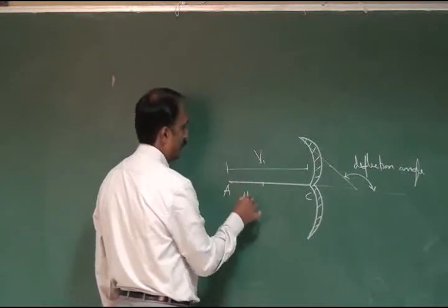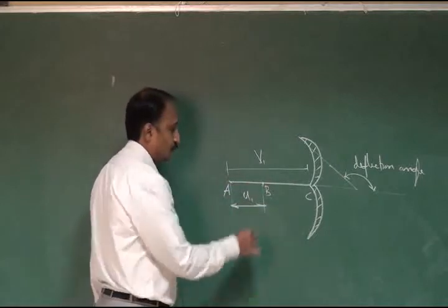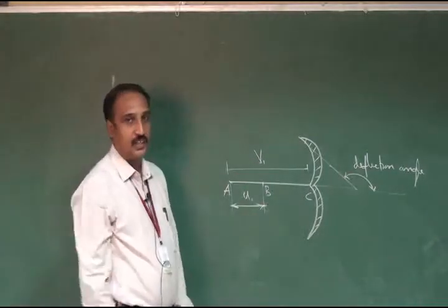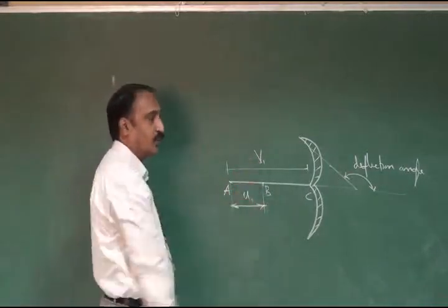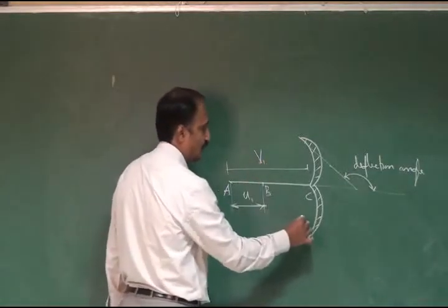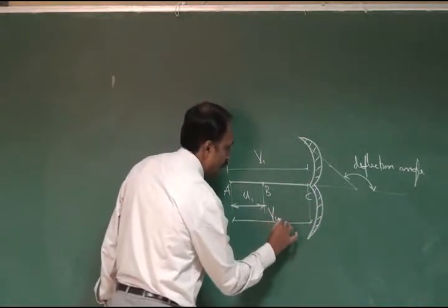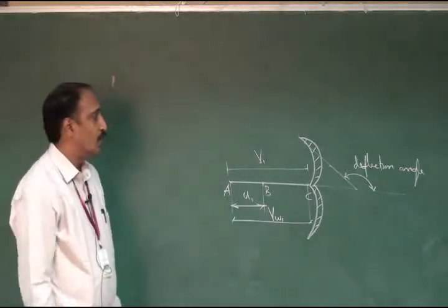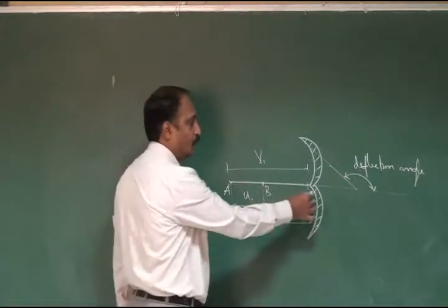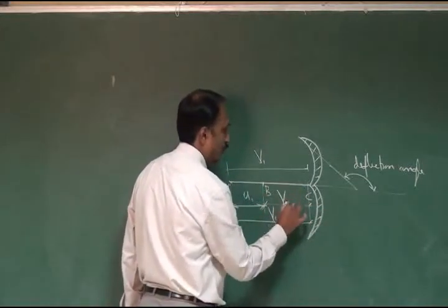This is the tangential velocity vector. Now absolute velocity is a horizontal component. There is no vertical component of the absolute velocity. So the horizontal component of the absolute velocity vector is equal to VW1. Now the difference between the absolute velocity and tangential velocity of the bucket gives us the relative velocity at inlet VR1.